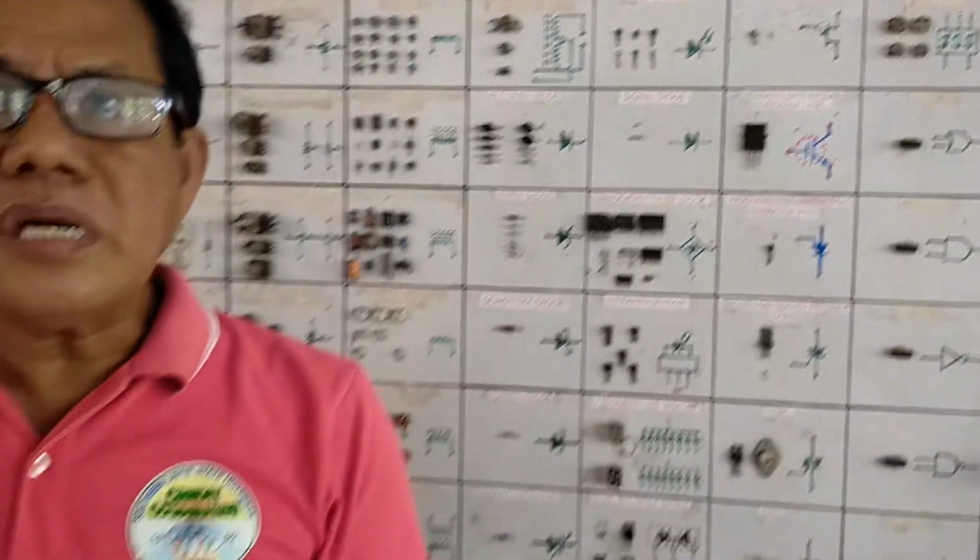So, what are these transistors and how do these transistors behave in electronic circuitries? Transistor, class, is a semiconductor device that has three electrodes. These are the base, collector, and emitter for a bipolar junction transistor. Then we have the gate, the drain, and the source for the field effect transistors. The term transistor is derived from a verb phrase, transfer resistor or transfer resistance.